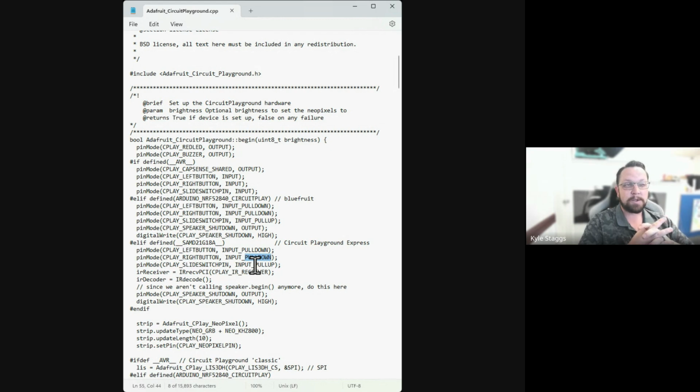A lot of modern circuitry is a little better because of having these pull up and pull down resistors in the design process, but much older electronics generally didn't have this, or something would skip to another track, or there's all kinds of weirdness that can happen, especially with static discharge. The state of an input button or something can actually be above 0 volts, and that can be enough to cause effectively a false trigger press or something, right?